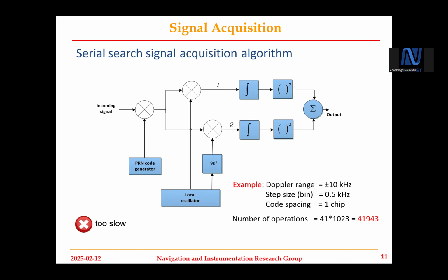Yes. We are using binary phase shift keying for modulation, right? Yes. So why do you need the in phase one? Binary phase shift keying only produces the signal in quadrature phase. You will see later when we track, this is just acquisition. You need two streams for the tracking later. You need two copies so that you see if you are getting high power. If you are not aligned in phase, you will get some of the signal power in the quadrature stream.